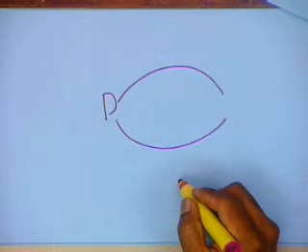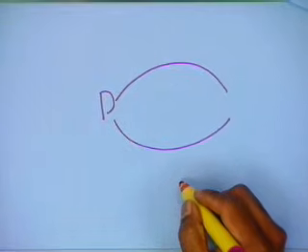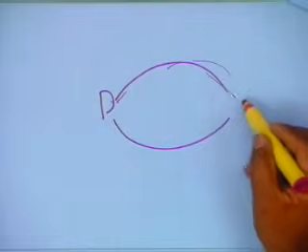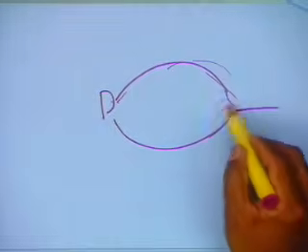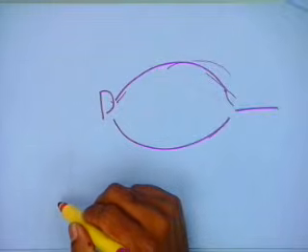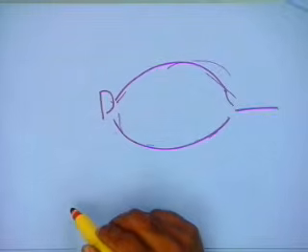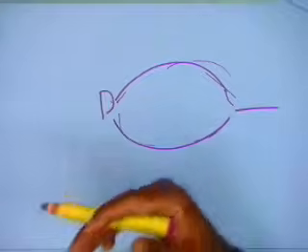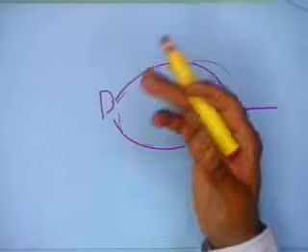If you have multiple paths, this is called a reconvergent circuit, where you are taking an output and it is following a path and going over here, and to satisfy one path you have to make some assignment, but to satisfy another path you have to make a different assignment to the same input, then your consistency may fail. And then you may have to backtrack and choose an option which you have not chosen.